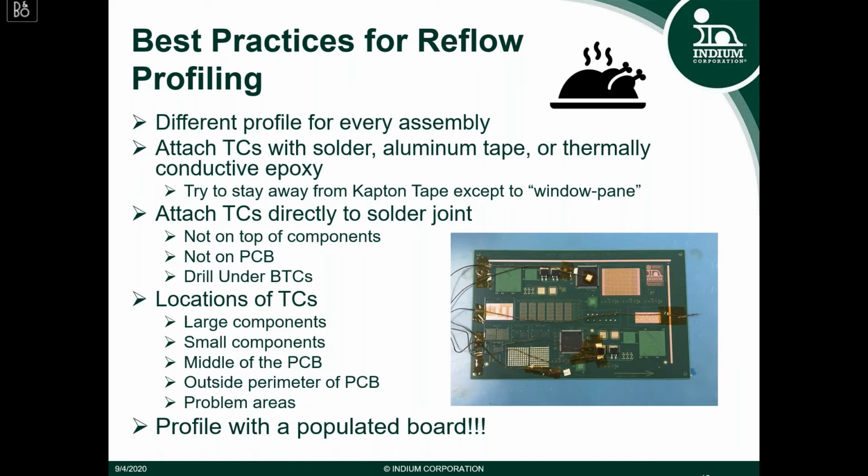For bottom termination components, this may seem difficult. However, it's important that you drill underneath your PCB to access the solder joint underneath the component. From there, you can attach the thermocouple through the board to the solder joint, and you'll get a more accurate reading.